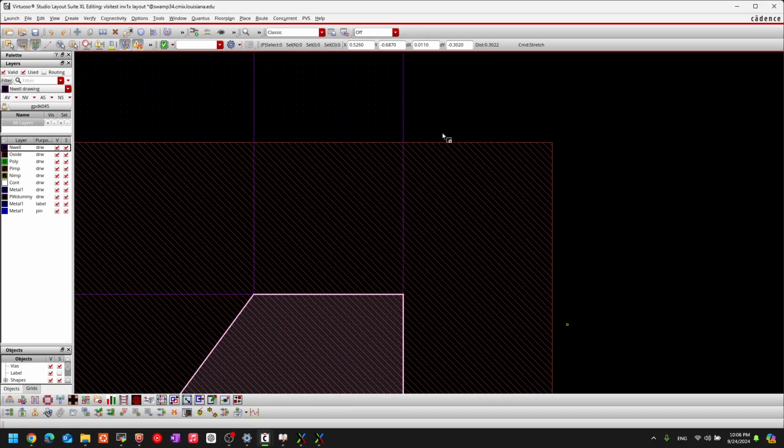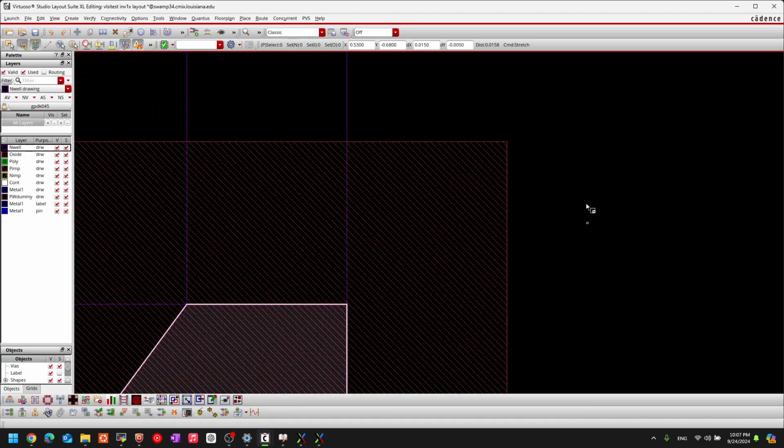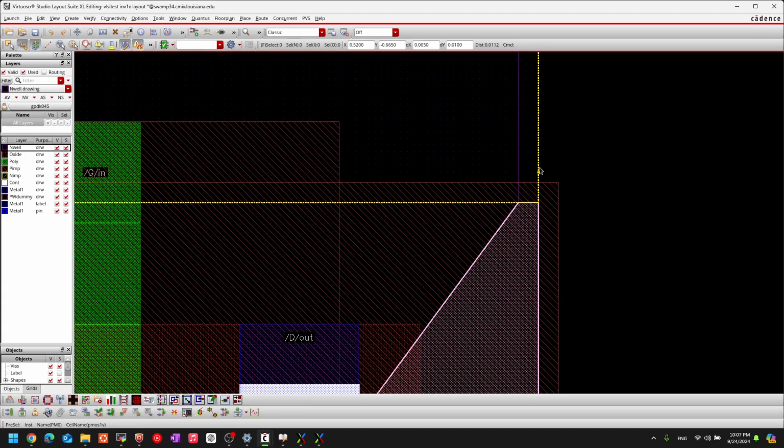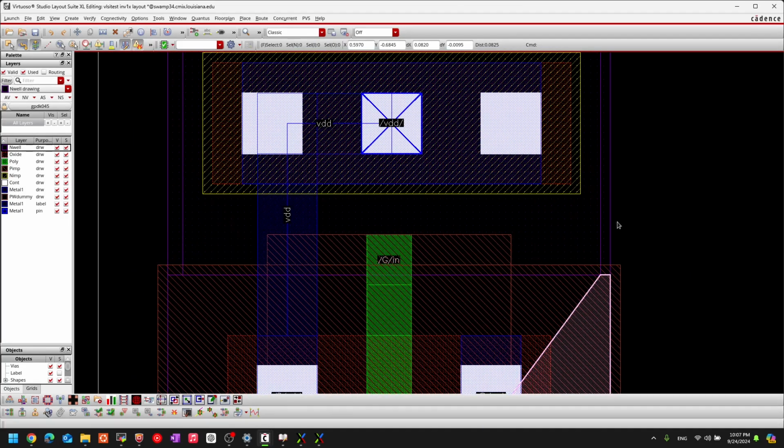So using the middle mouse button, click on this edge, and you could just stretch the end wall region. And once I stretch the end wall region, I could double click. Whoops. I double clicked and I placed or stretched the layer itself.